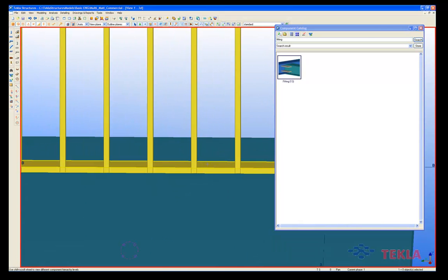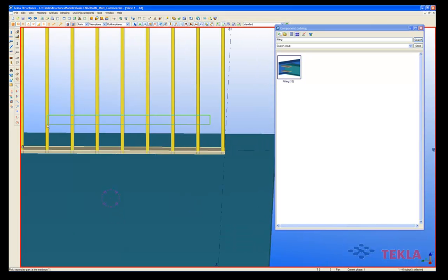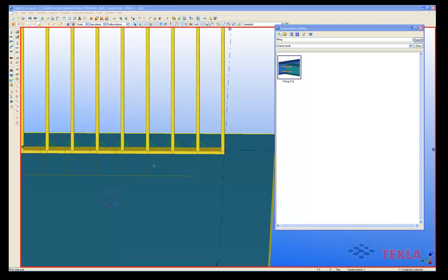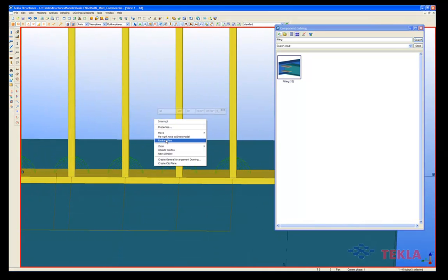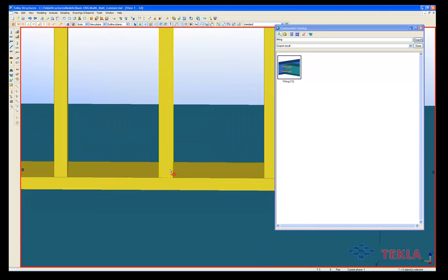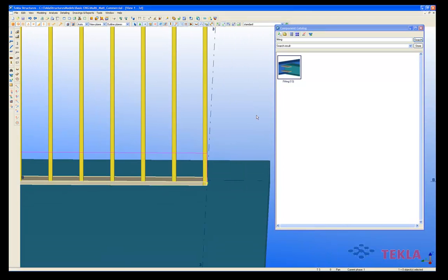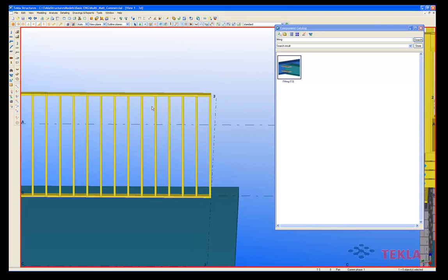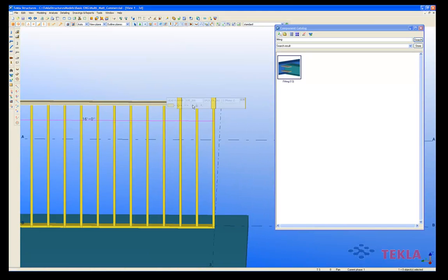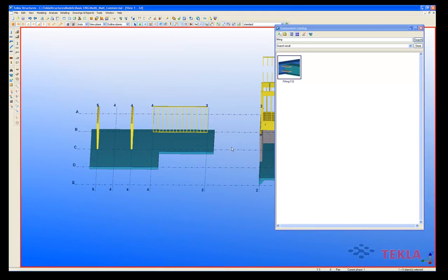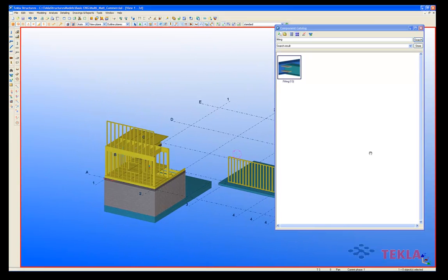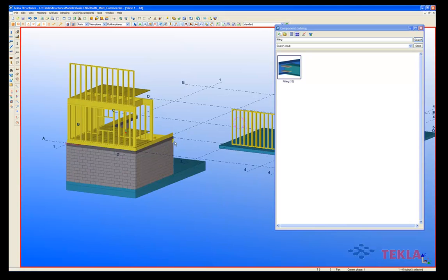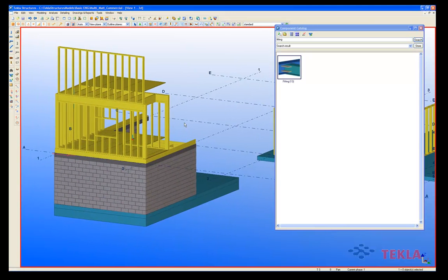Now also on these stud walls, you may or may not notice that we don't have them cut back within the component, but I'm just running a simple fitting command here that will then get your cut lengths to the proper length for your bill of material and such. And then you see here that it cuts back to the face. So the intention is to just run it that way, and we are doing further development on these components, and we want to keep making them more and more intelligent. Working with several customers specifically to find out more functionality. So there you go. That's a quick view of some new components in 16.